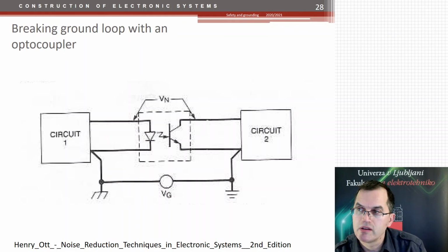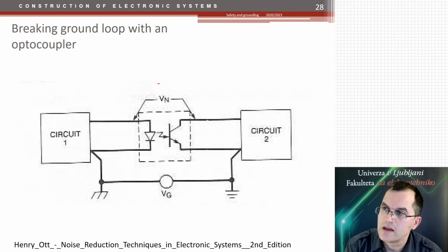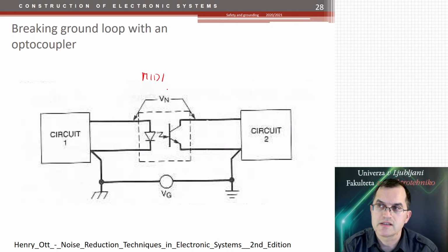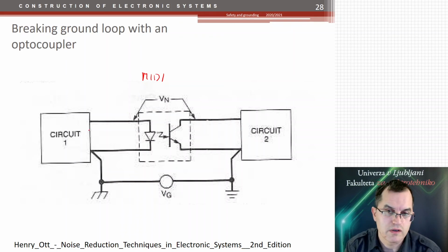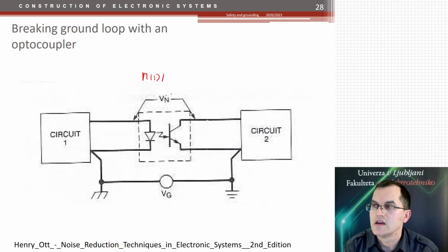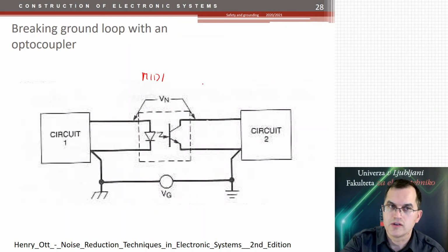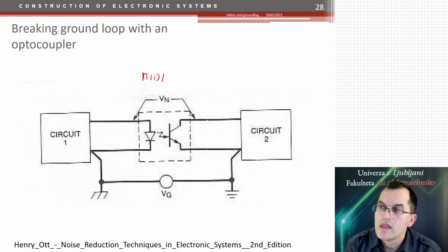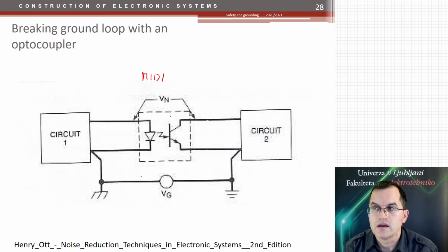For example, if anyone is working with music, the so-called MIDI interface that connects different audio instruments or any music instruments together, transferring digital information about the pressed key, tone, and stuff like that. They are all galvanically isolated by these optocouplers, so they don't form ground loops.